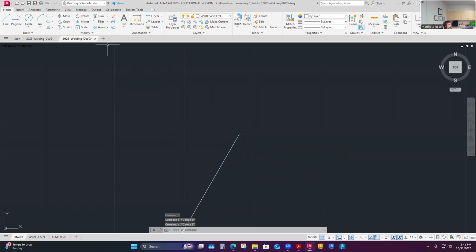So here's what I have to remember. With the fillet command, I need to usually put R for radius. I need to choose the command and then tell it the radius. And I wish the prompt said select radius, but it doesn't. So I usually have to remember to hit R for radius. And then I'm going to say it's a 0.25 radius, quarter inch radius, enter. And now I can choose this.